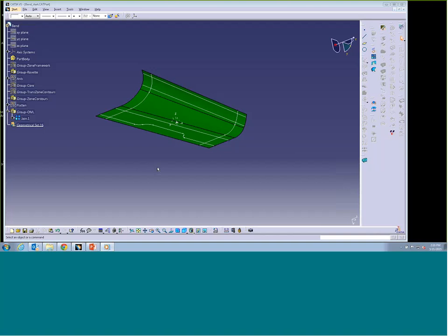And secondly, we need to somehow determine the ply boundaries. And typically, it's done by creating a network of curves. So you see there is a bunch of curves placed on the surface, which define the boundaries between different laminates, different thicknesses. Again, how you create it, you can use CATIA if that's your main CAD system, or just as well, you can use any other and import it into CATIA.